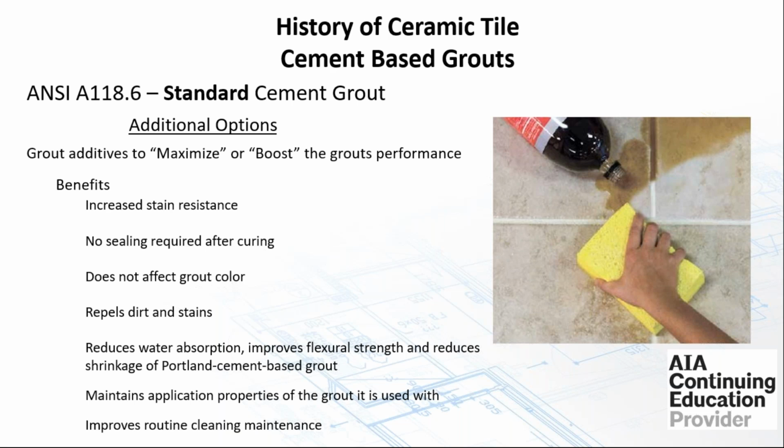These boosts or additives do not affect the color, it stays the same, in some cases even intensifies it. It does help repel dirt and stains, it reduces water absorption and gives it a better flexural strength, and also reduces the shrinkage of some of the Portland cement grouts.